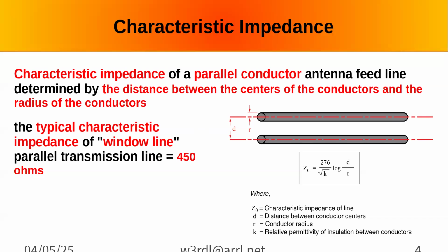The radius of the conductor, as that increases, it's going to decrease the inductance. So that's part of that thing about if you increase the diameter of the conductor, how it affects it. That's one of the effects. But the capacitance also increases as the surface area, so it's more like the square.